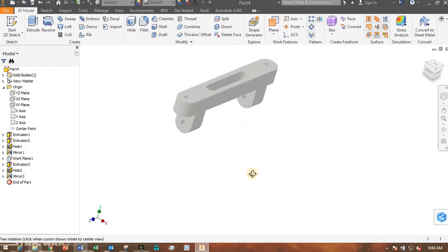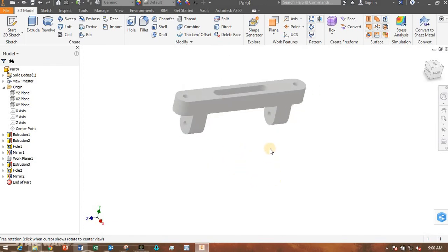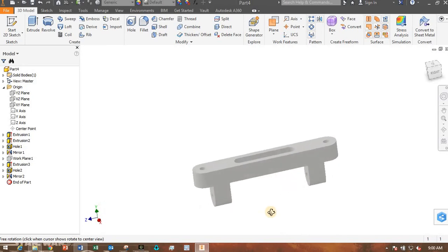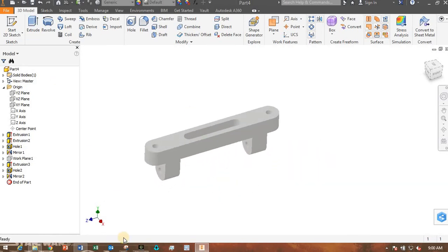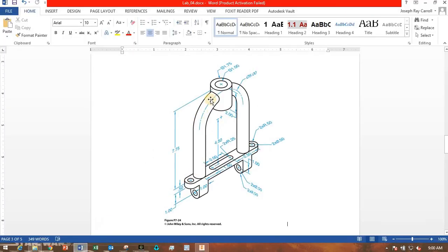Okay, there's that idea. Now, basically the last thing that I need to do is add in the part that's a little more complex. That's adding in this curved part here. Again, let's ignore that we have this cylinder up here, and let's first just do this one here. Alright, well, I can see this is where a sweep feature would be very nice. I cannot just do an extrusion, and I cannot just do a simple revolution, but I can do a sweep.